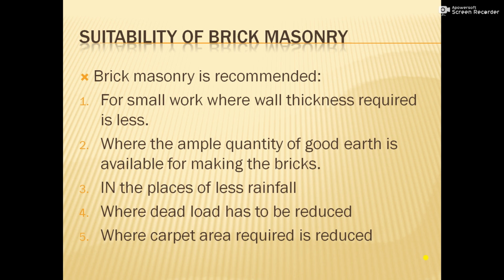Next, where the dead load has to be reduced. As stone has a great weight, the dead load of the structure increases. So where we have to reduce the dead load, we use brick masonry. And the last one, where the carpet area required is reduced. So under these 5 conditions we use brick masonry in construction.